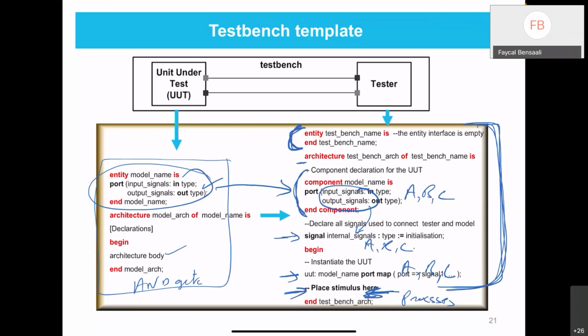And the good thing with most of the software tools used with FPGAs or used to write VHDL code is when you create a test bench, it will ask you, okay, what do you want to simulate? So you may have multiple files in your project. You may have multiple VHDL files. For example, if you are working with components, so you have two components and then you have the main file. It will ask you, what do you want to simulate? So if you have just one file, an AND gate, let's say, you will select the AND VHDL file.